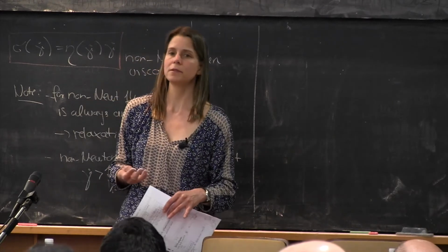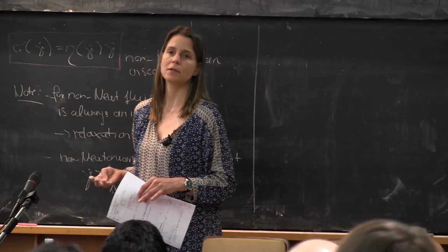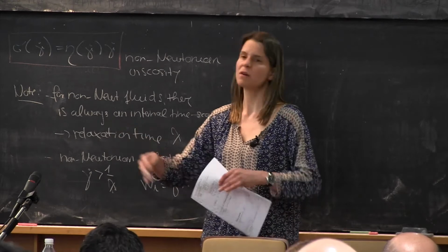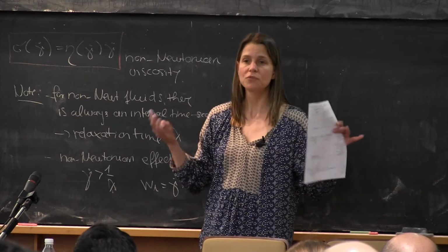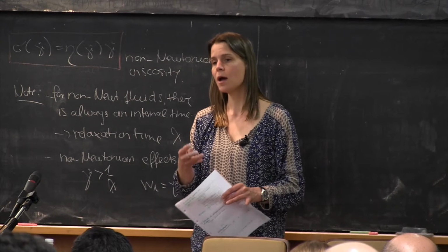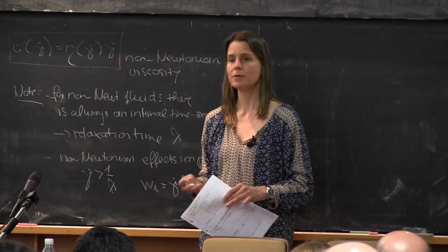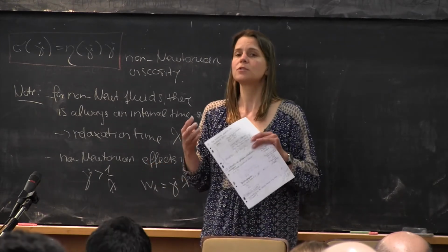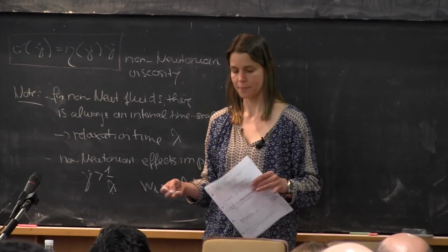So what people who do rheology did is try to make their life a little bit easier. They define rheological flows. They say, okay, these fluids are very complicated, I don't really know what to expect. I will only test them in defined flows, because these flows have certain symmetries. And if I use the symmetries of these flows, I can make some assumptions on my stress tensor. So this will make my life much easier. Typically this is a simple shear flow and a simple elongational flow. And strictly speaking, only in these flows you can define the material parameters that you will measure.